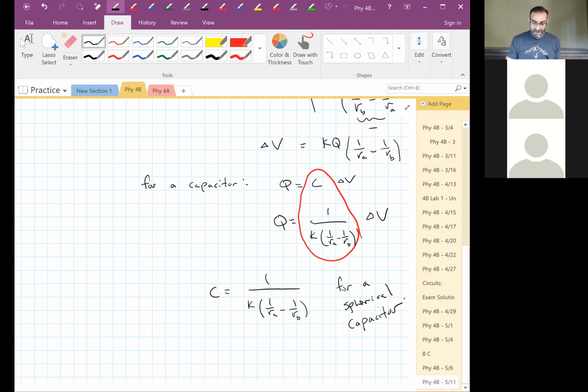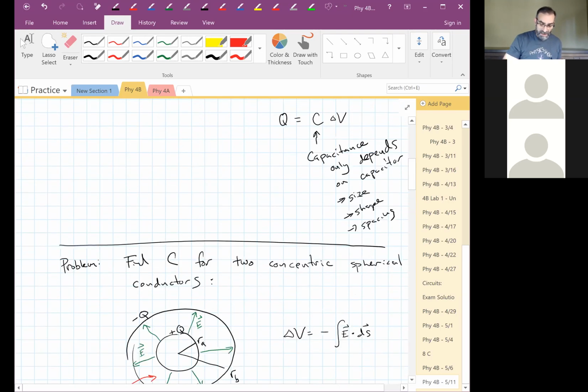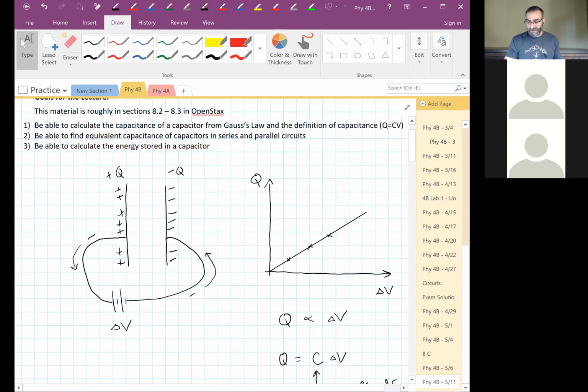Okay. So a capacitor, what does a capacitor do? Let's just go back and think about it for a second. A lot of people say a capacitor stores charge. Really, what it does is it stores charge separation, right? It stores energy. It took energy to separate those charges. Those negative charges, those electrons all pushed onto that one plate, they repel each other.